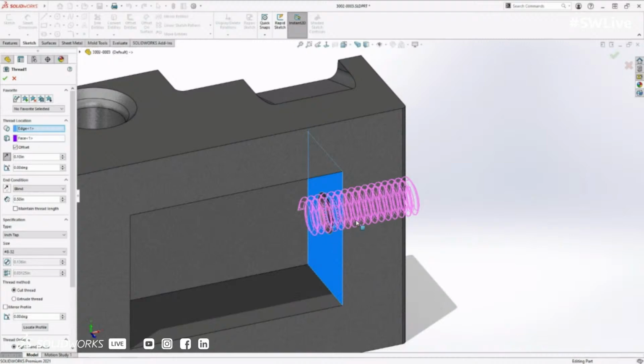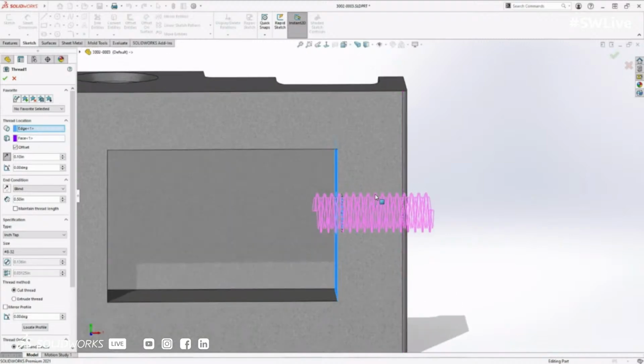When you use this thread tool, one of the things I noticed is you sent me all this video of you modeling this part up, but I thought it'd be cool to go into here and take a look at this. I noticed the threads don't start at this face and end at this face. You make sure that the thread goes beyond the extent of the material that you're cutting it through. Yep. It's really embarrassing the first time you do this and you go to thread a fastener in and it doesn't thread in and you realize you were short by 15 thousandths for the thread breaking all the way through it.